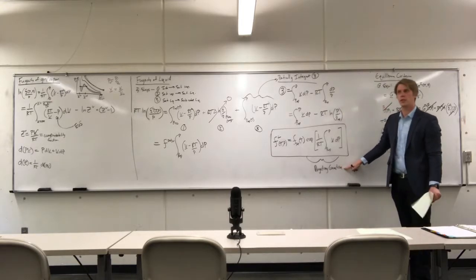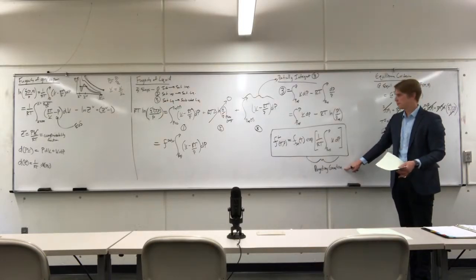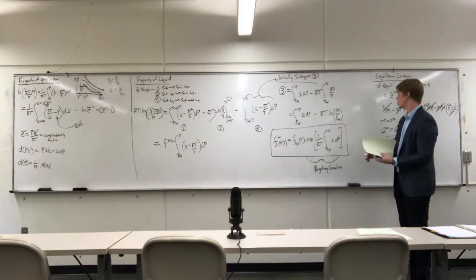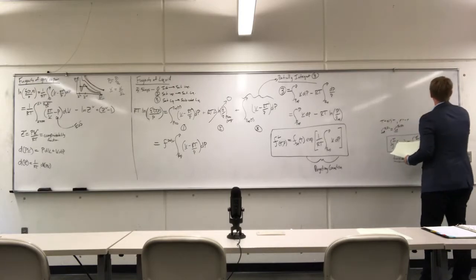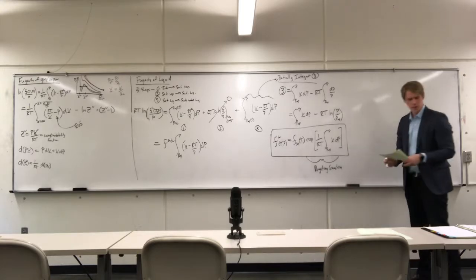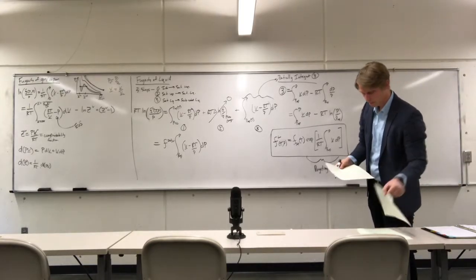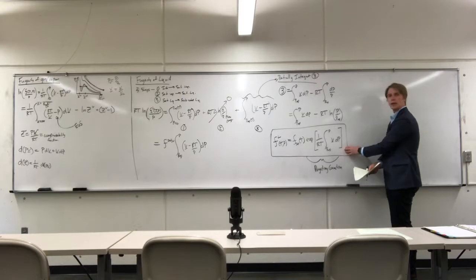Generally, this only matters for relatively high pressures, let's say 1,000 psi or higher. But it's very easy to calculate to see when it should become impactful. So there's a couple of approximations that we can do to that Poynting correction. This is an exact expression. We have made 0 assumptions. So this is valid across all phase transitions, whether it's solid liquid, vapor liquid, whatever the case is. This expression is fully valid. It's for a single component, so I guess it could be gas solid. This is a valid expression as well.